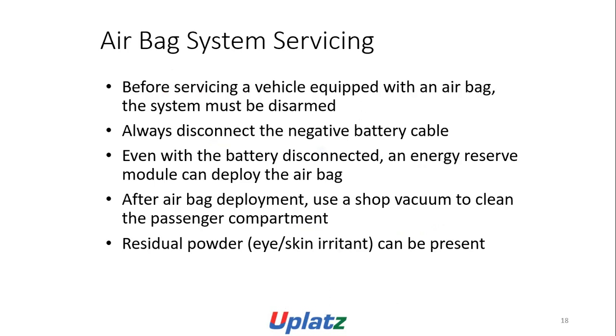Airbag system servicing. Before servicing a vehicle equipped with an airbag, the system must be disarmed. Always disconnect the negative battery cable. Even with the battery disconnected, an energy reserve module can deploy the airbag. After airbag deployment, use a shop vacuum to clean the passenger compartment. Residual powder, dust, and skin irritants can be present.